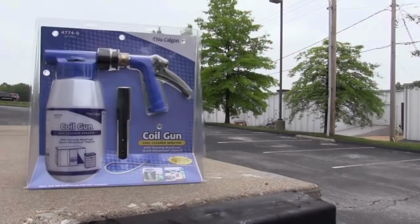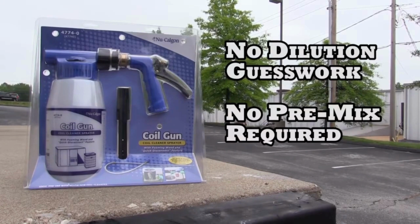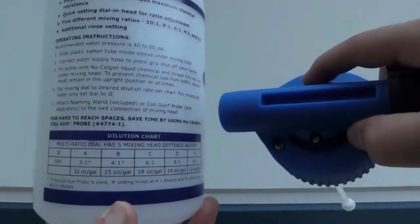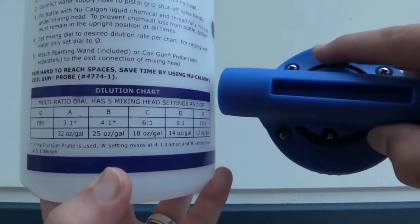Use of the New Calgon coil gun takes the guesswork out of the dilution process. Unlike other sprayers, which require you to combine water with the coil cleaner in a separate step, the coil gun does the mixing for you, thanks to the specially equipped mixing cap that siphons the cleaner through the coil gun when the sprayer handle is depressed.